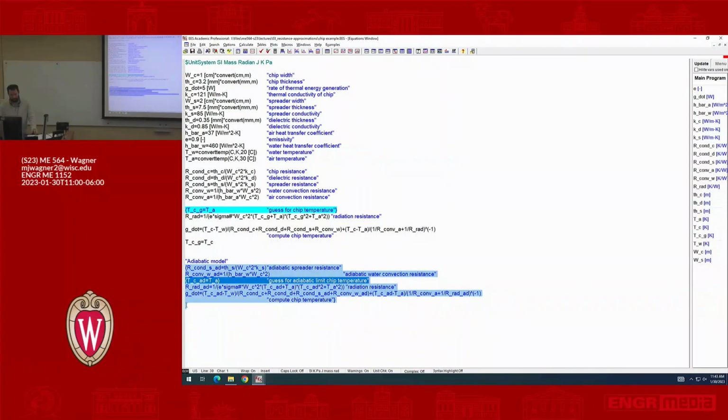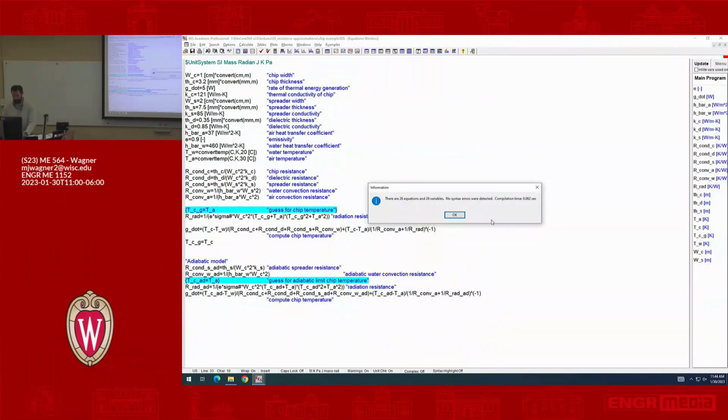Again, everything's the same except I've now added in a modified conduction and convection resistance. I again need to guess: going through this process, I need to guess the adiabatic temperature and the resistance, and then calculate the energy balance again. Let me just see. Hopefully this works. Yep.